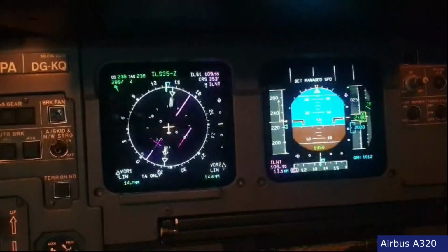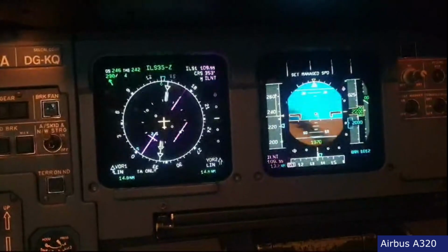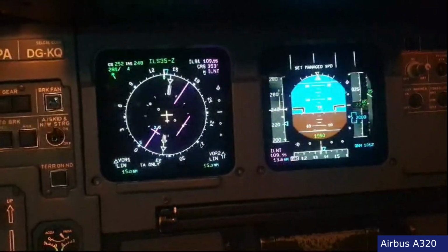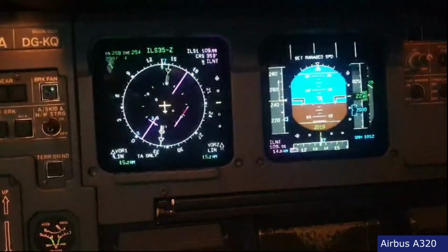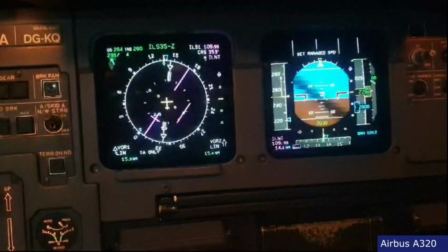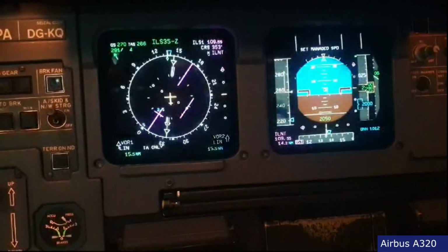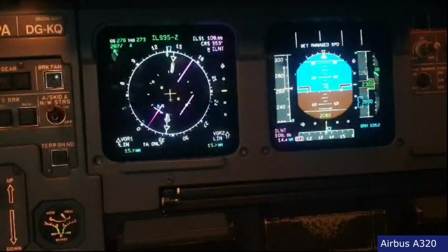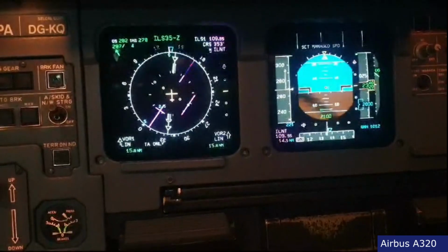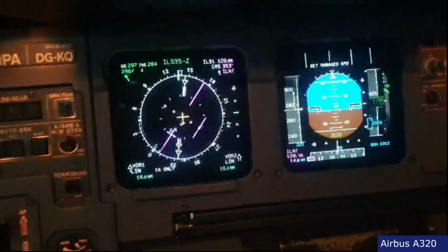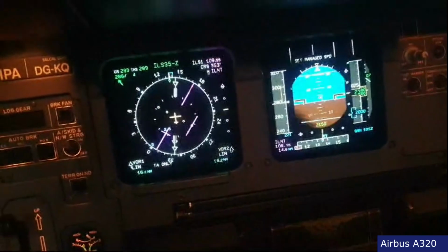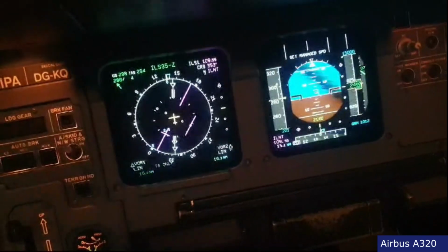In the home simulator it was maintaining 5 degrees. Look at the pitch, is now decreasing. We are 4 degrees, we're nearly 2 degrees now. You see the pitch is going down quite fast, I would say. With the speed increase, the pitch is going down. Still the altitude is climbing, so what is the aircraft tracking at this point? Is it tracking the altitude? It's not tracking the pitch.